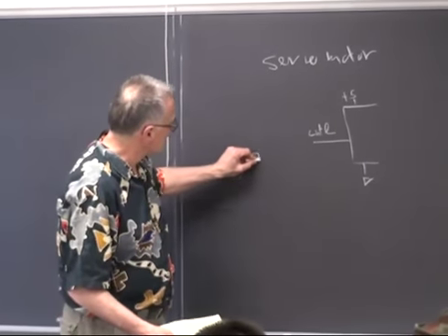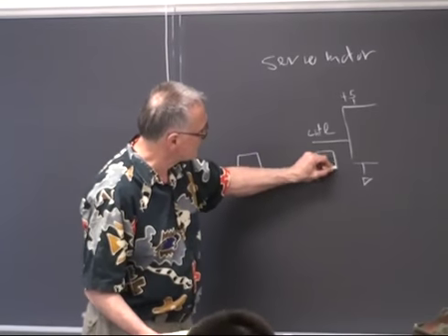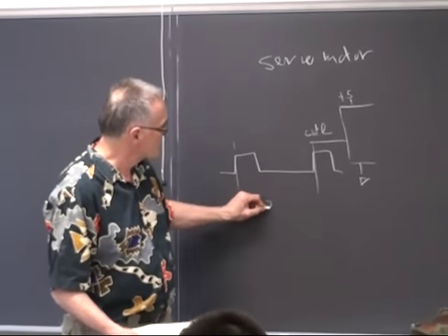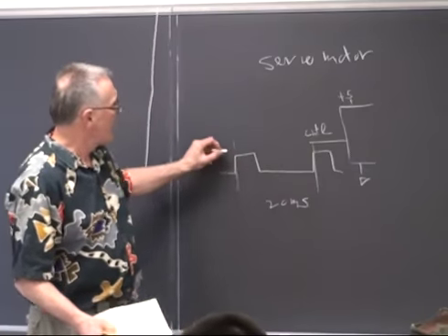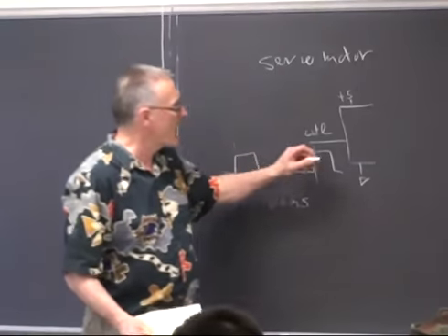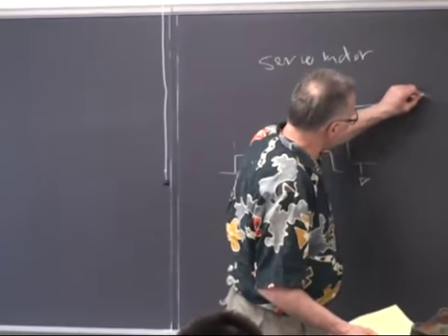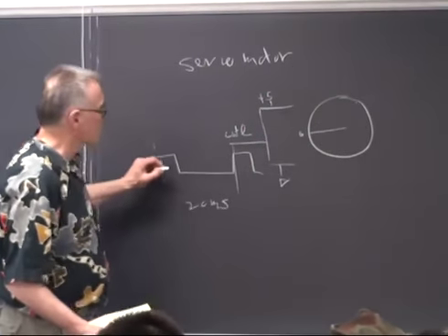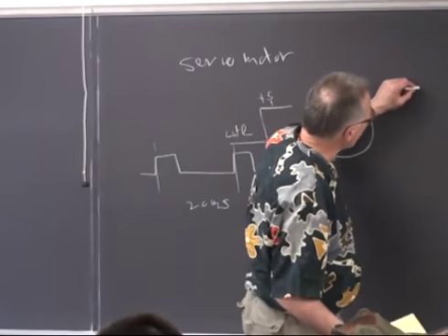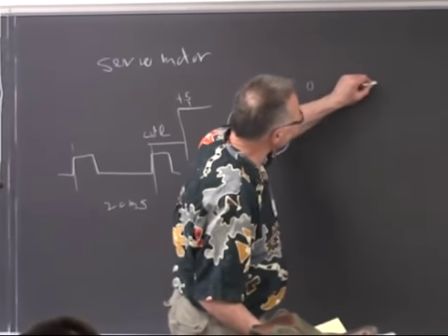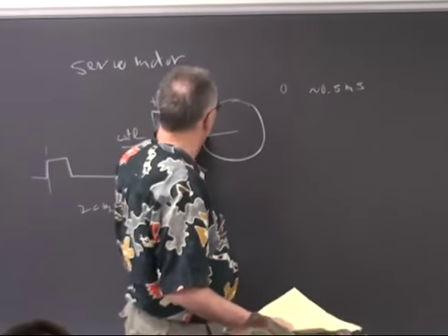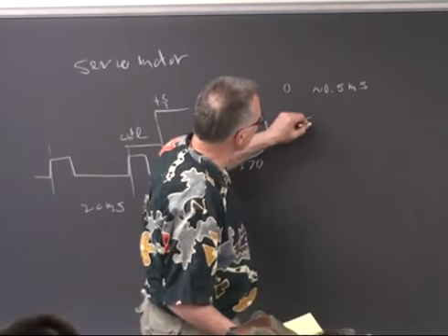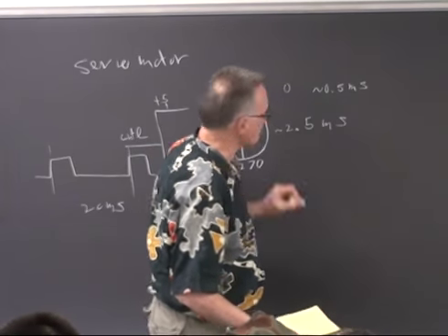The control lead is a pulse width modulated system with a minimum time between pulses of 20 milliseconds and a control such that 0 degrees corresponds to about a 0.5 millisecond pulse width, and 270 degrees corresponds to about 2.5 milliseconds.